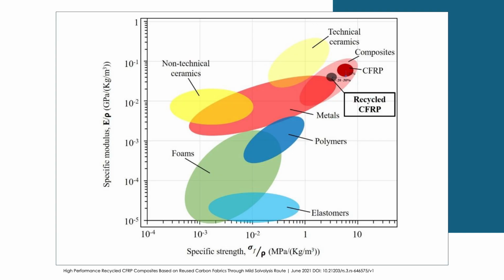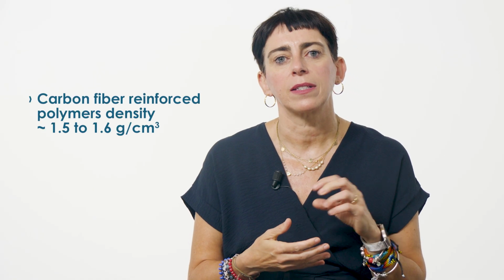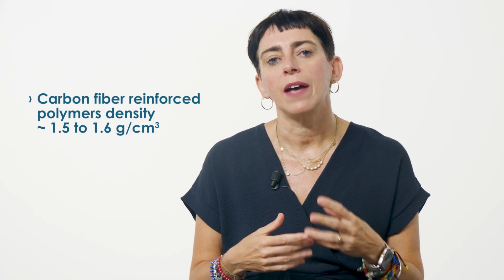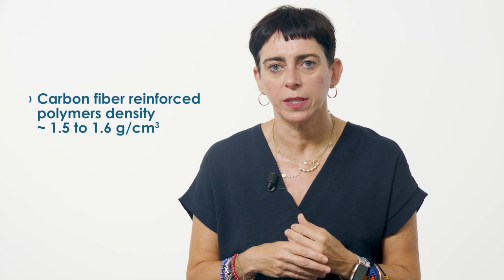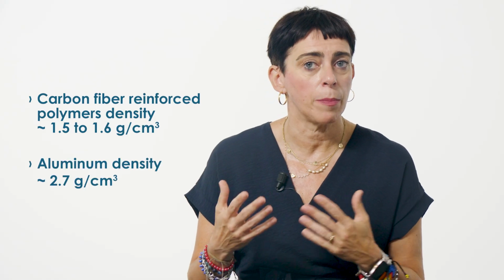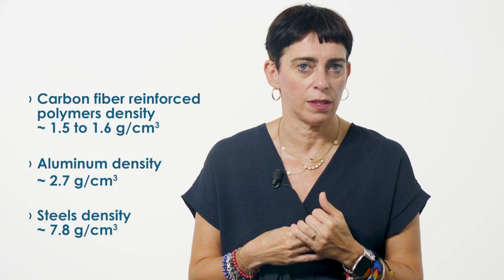Notice how composites sit in the upper right part of the diagram. That position shows their advantage: high stiffness and strength, but a much lower weight than metals. For example, carbon fiber reinforced polymers, or CFRPs, have a density around 1.5–1.6 grams per cubic centimeter. Aluminum is about 2.7 and steel is 7.8 grams per cubic centimeter.